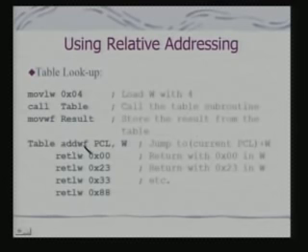This instruction, ADDWF, is a routine instruction in the sense that it can be used with any register, but here it is interesting because it is using PC, the program counter. So, PCL, part of the program counter, is an operand. Now, this feature is not typically supported in many instruction sets. That is, you really cannot use PC as an operand in an instruction, but PIC provides the support for this kind of instruction. So, what is it doing now?